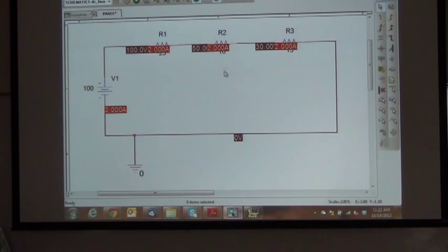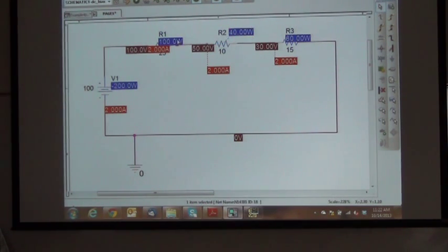And you can click current. It'll show you the current through each component. And you can even move those around if you want. And you can hit watts, will give you the power through each component. Multisim does not do this. In Multisim, you would have to come in and you'd have to put a voltmeter or a wattmeter on every single node. So if you can deal with the little bit of extra work involved in opening up the schematic the first time and creating the simulation profile, then PSpice is a lot better from that respect.